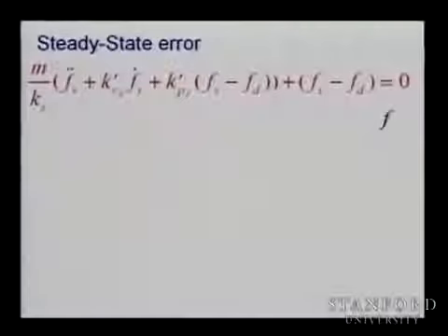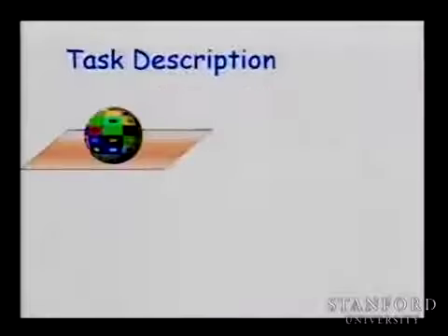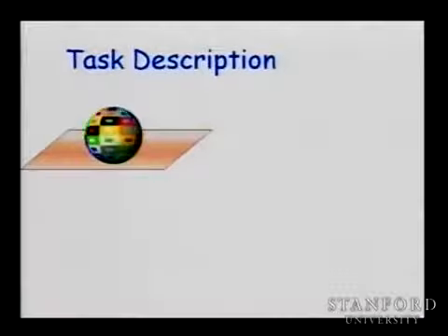And these depend on, I'm going to skip this, these depend on the relationship between the object you are assembling. So if you have a sphere, and if you want to put the sphere on a contact, you lost a degree of freedom, right? You cannot move in the z direction. You cannot move in that direction. You can still slide on the xy plane, right? So how many degrees of freedom of motion you have now? Imagine the end effector is holding the sphere on the surface. How many degrees of freedom you have?